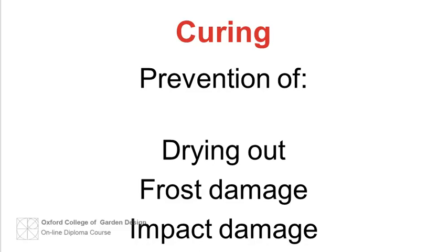In summer, foot traffic can use concrete drives and paths after 3 days, cars after 10 days, and lorries after 28 days. These times should be increased to 4, 15 and 40 days in cold weather.